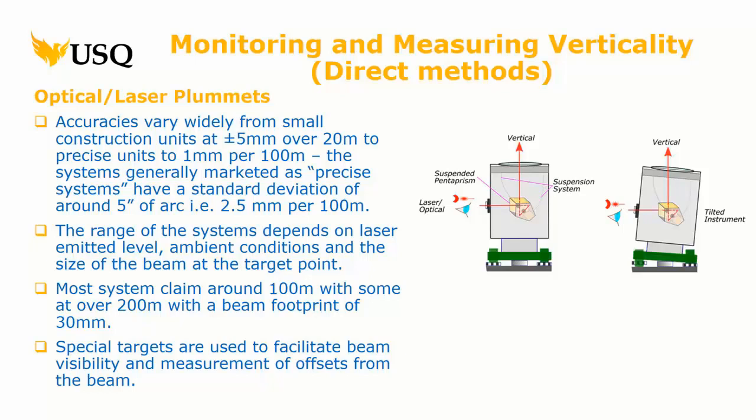For the surveyor, of course, we're presuming the builder makes mistakes and everything else, so you've got to be 3 to 5 times better. But there are units, and I think the study book outlines one of them, I can't remember the name of it, that's running around 1 millimetre per 100 metres, which is pretty good. Of course, you pretty much get what you pay for.